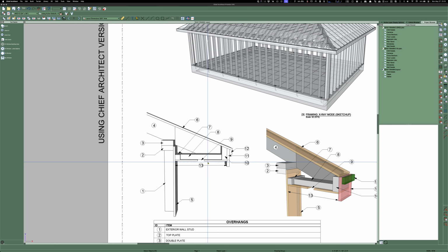And it's going to come out the distance of the soffit. And that's where your subfascia is going to stop so that you can attach your soffit to the subfascia here and here. And then your fascia board goes on the outside of that. So regardless of what the plan says and regardless how Chief Architect would dimension, your overhang is not going to be to the outside of fascia, because there's no way I'm ripping down pre-primed concrete soffit to make it fit something that a piece of paper, like a set of plans, says, oh, it's got to be to the outside of this. No. This piece of soffit dictates that.